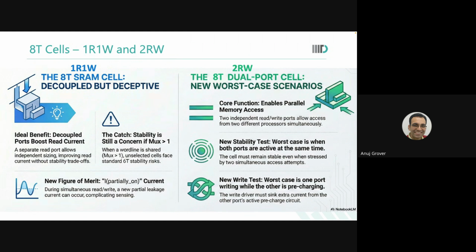Is that clear? So you cannot anticipate whether 0 will come here or 1 will come here. No, you can't. You understand your circuit. You see which is the worst case. And then design your stimuli in such a way that that worst case is activated. Design your verification plan in such a way that that worst case is activated. Then something will happen. Is that okay?